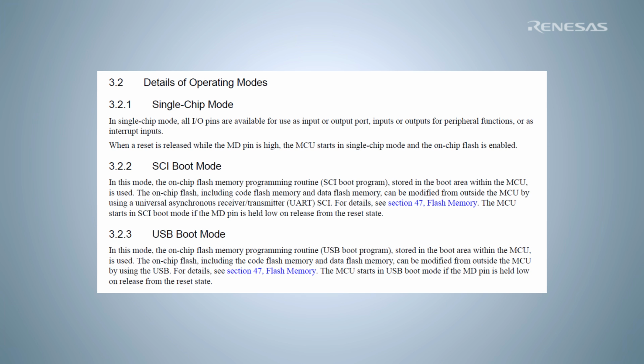The EK boards are configured to start in both single chip mode or boot mode. The single chip mode basically means the MCU will start and resume the program it contains. For the boot mode, the MCU starts, and instead of running the application, if there is one, it waits for specific commands that have been designed to execute in boot mode.